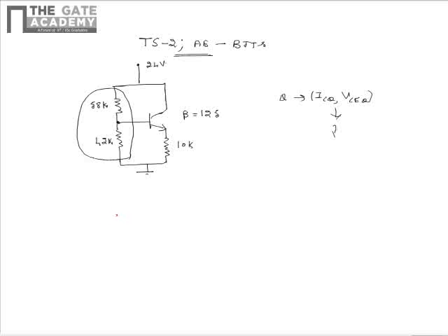So upon finding the Thevenin's equivalent, we see that the circuit gets simplified as shown. The emitter is connected to 10k ohm resistor as before and the collector is connected to 24 volts supply, but the input supply and the base circuit part is connected to a Thevenin's equivalent, upon which we see that the Thevenin's voltage is 10.1 volts and the Thevenin's resistance is 24.36 kilo ohms.